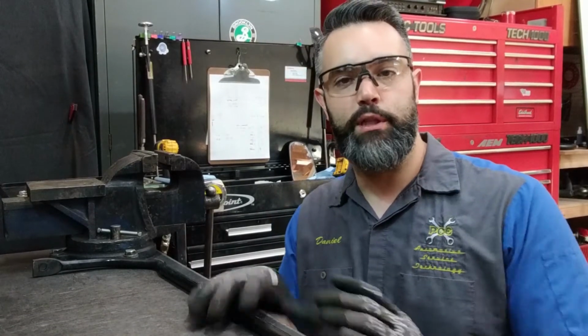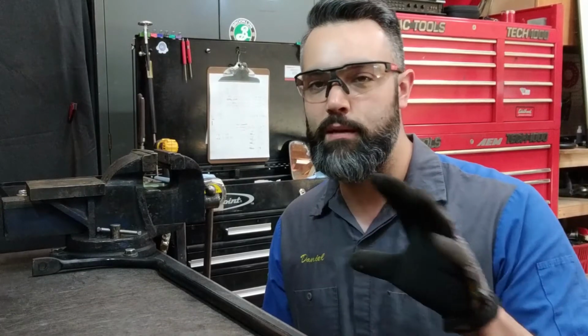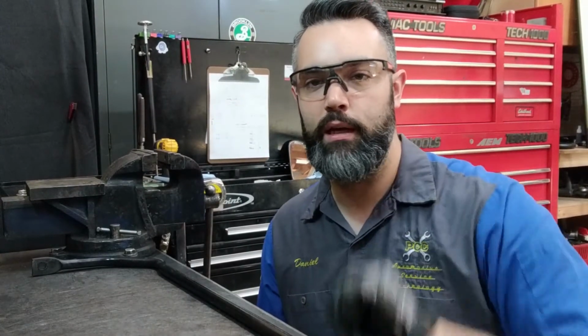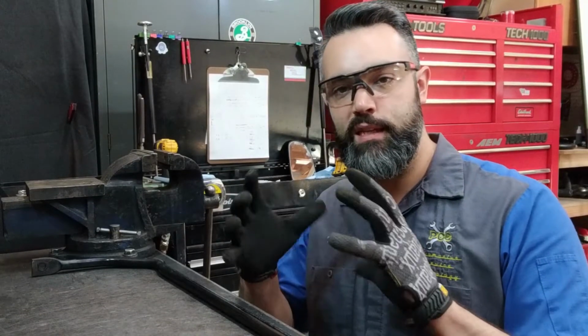All these things can be put together and interpreted by a module that can send an output command to the active control sway bar, with all these systems giving inputs, and that control module outputting a signal or a command to the electronic motor on the active control sway bar that can actively adjust stiffness while the vehicle is driving through different scenarios without the driver input. It's doing it automatically through the function of the other sensors in the system.